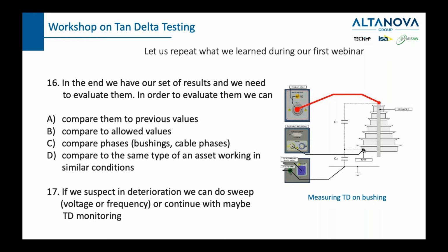If we test the cable, the phases should all have very similar values. Or we can compare these values to an asset working in similar conditions and having a similar structure. So these are the ways how we can evaluate if the results are okay.